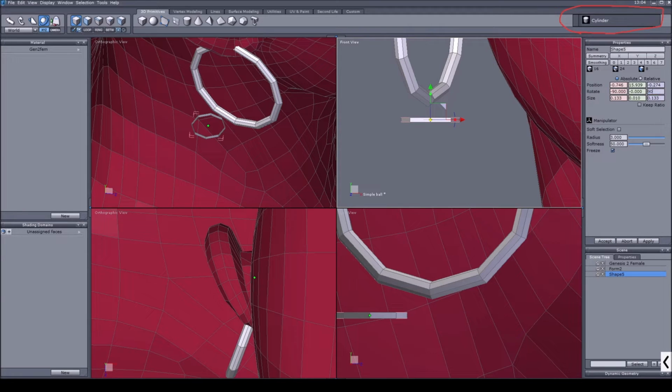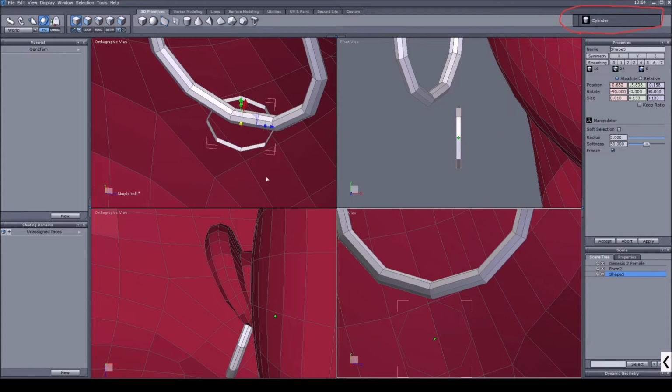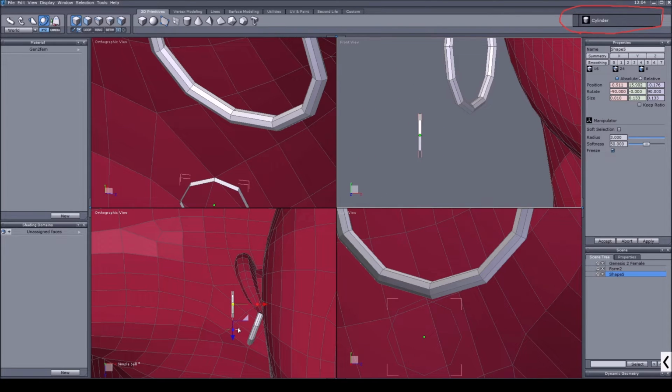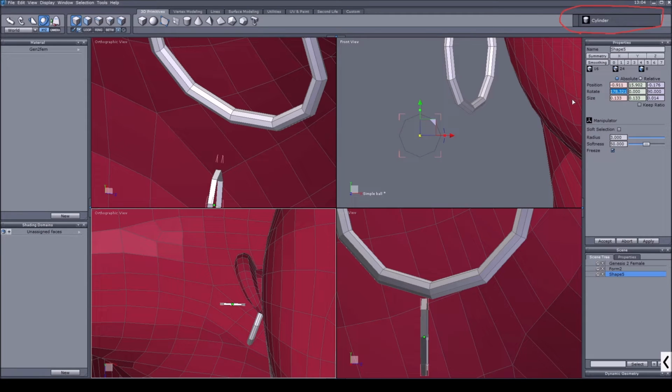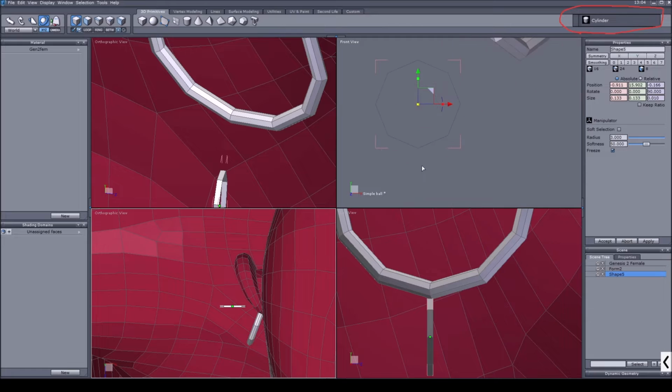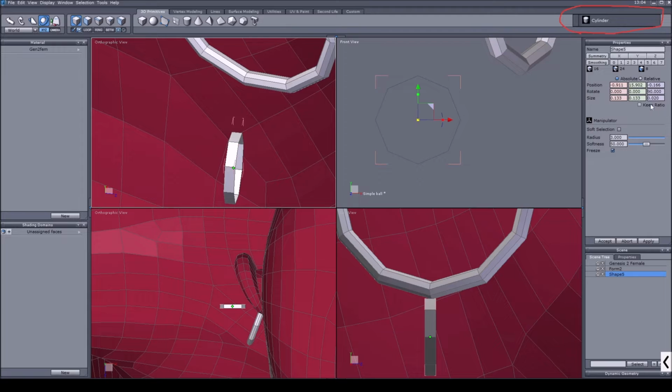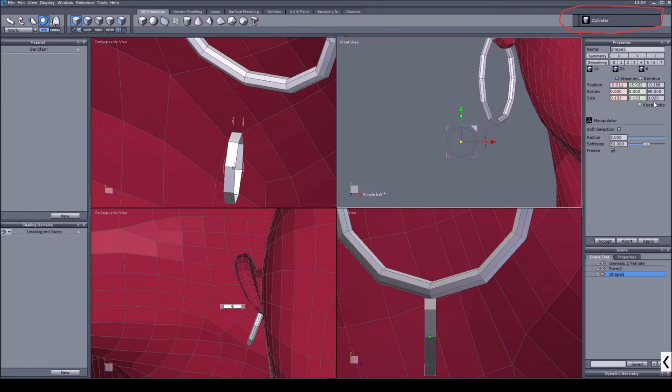Gonna turn this 90 degrees. Now it doesn't jump for some weird reason. I don't know. Okay. We're gonna make a chain link from this. So we're gonna turn this 90 degrees as well. Okay, so far so good. We're going to thicken this to 0.02 as well. We wanted to have it the same. Actually, no. Let's do 0.01, so it has half the thickness of the hoop.